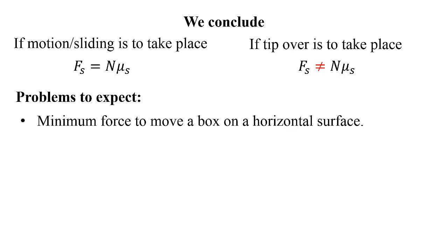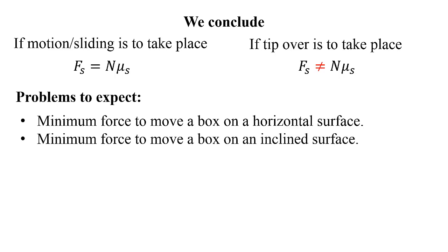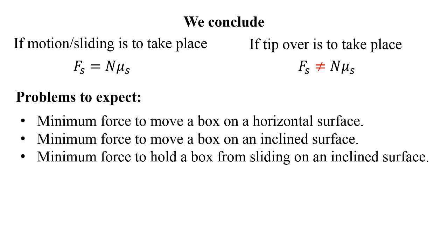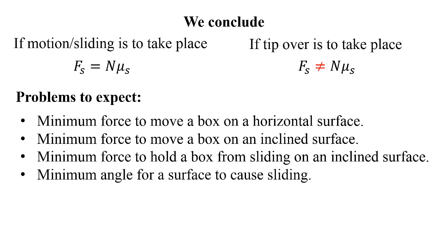Another problem can ask you for the minimum force to move a box on an inclined surface. One problem can ask you for the minimum force to hold the box from sliding downwards on an inclined surface. A problem will ask you for the minimum angle for a surface to cause sliding. So you have an inclined surface with a crate on top, and you are able to increase the angle of this inclined surface.